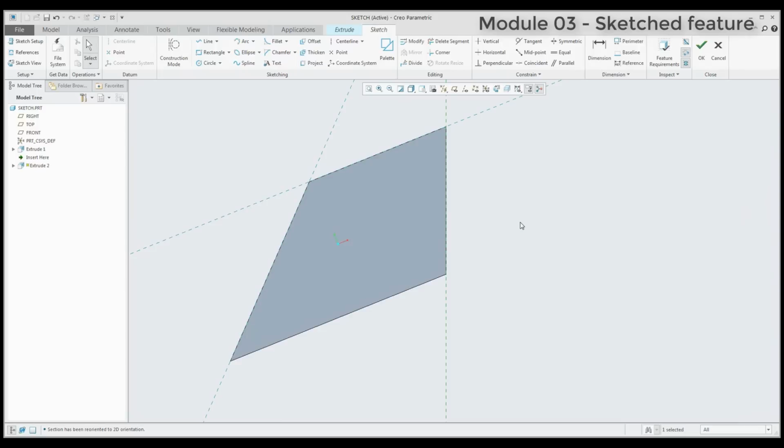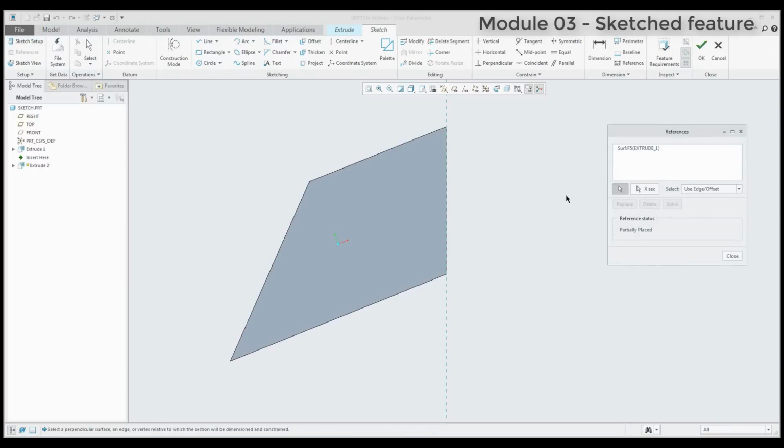And here is the question. If you delete some reference, yeah, I will delete some reference. And for example, later you would like to add this reference, because if you would like to create a line, you would like to directly snap to the existing lines. It's not a problem. You can select the reference window and you can select any line, surface or edge directly from 3D and add these features as the reference.